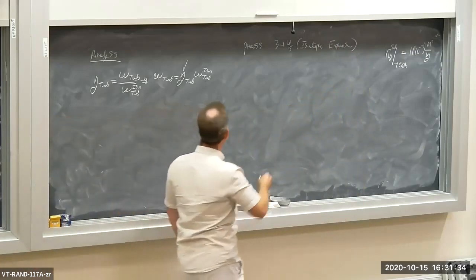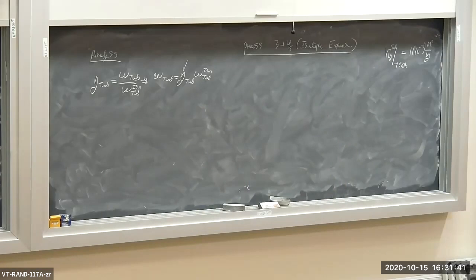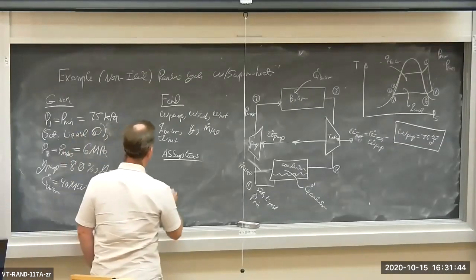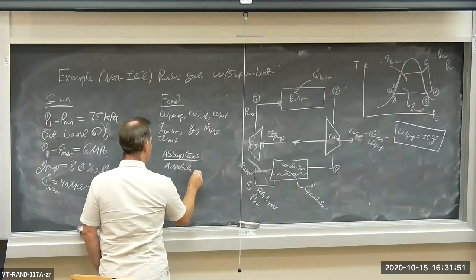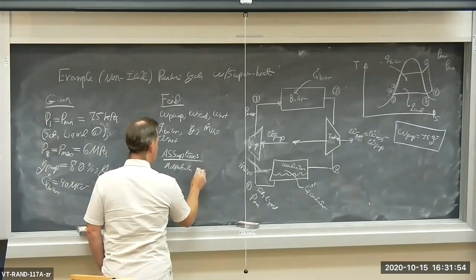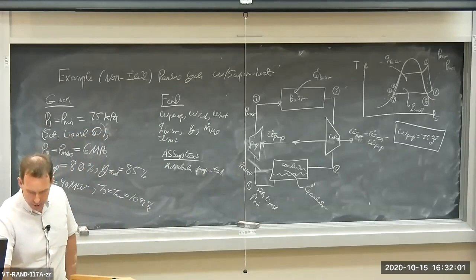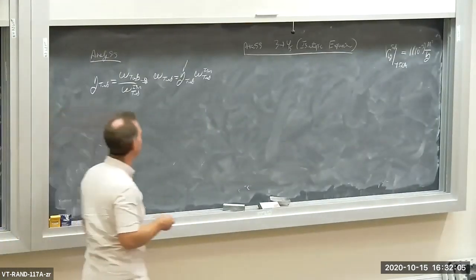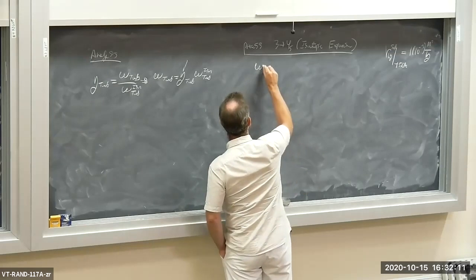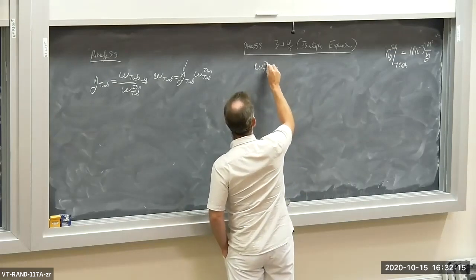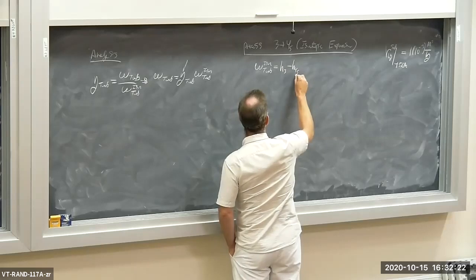Apply the energy balance. I guess I better write in the assumption, I'm assuming my pump and my turbine are adiabatic. Adiabatic pump and turbine. Else, got to get the first law right. Let's see, I'm going to factor out the mass flow rate, and I get W turbine, and this is for the isentropic turbine, is equal to H3 minus H4 sub S.